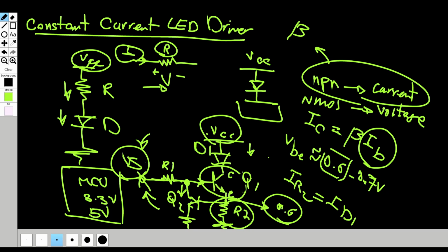And as we discussed, V equals IR, based on Ohm's law. So as we get more current through this resistor, we get a higher drop, right? When we get a higher drop, there will be more base current through the base of the Q2 transistor, and subsequently more current drawn out of the base of Q1 through the collector of Q2.